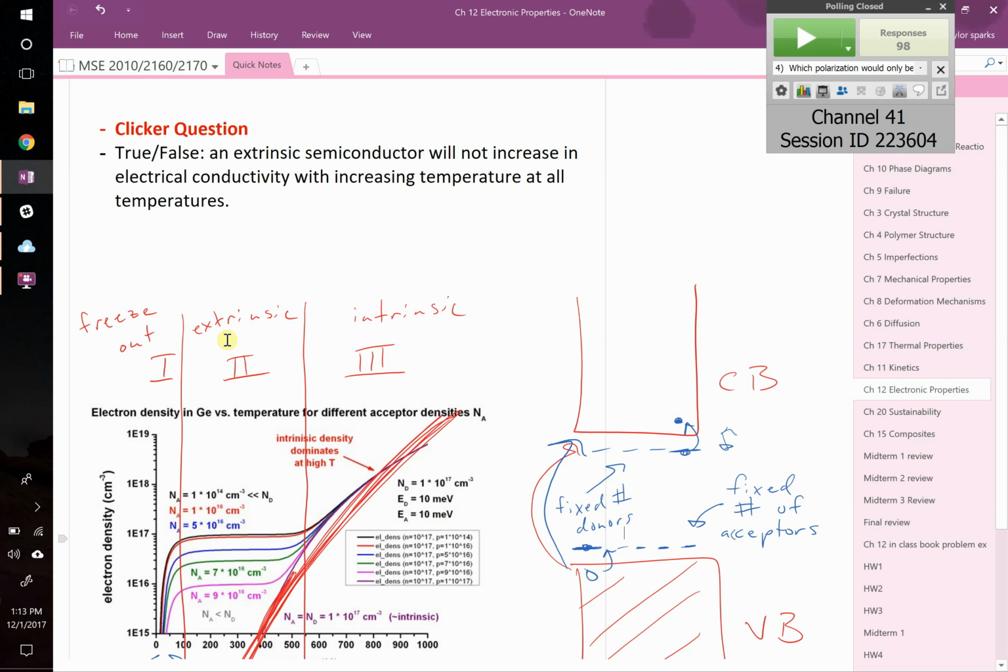Okay? And then will it jump up to the fixed donors, or directly to the CB? I guess it would go to these spots first because, again, this is like a phosphorus that has 5 electrons. It loses one, so now it's positively charged. So technically, it would still like to grab an electron if one becomes available, right? So that is going to be a priority destination if you're going to start to hop up. You will start to ionize those. Okay? Any questions? Yeah, Jaron.